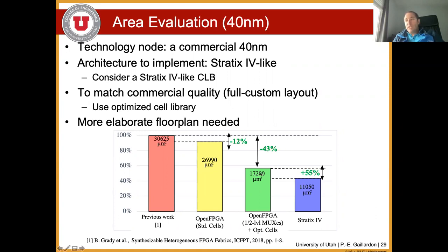But with our approach, which is a post-technology mapping approach, and adding a couple of custom cells, we can really bring things down to an acceptable level. In that experiment, which is already 2 years old, we were 55% bigger. Now we're almost on par in terms of size because one can push the tools further and do some better design shaping. So we are bigger, but in the 10% range compared to what a commercial FPGA could be.